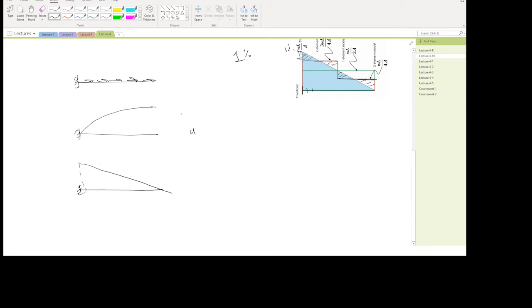So both of them are related. The stress or the strain is the rate of change in the displacement. And if you look into the parabola, you'll see that the derivative of the parabola at this point is 0. So this is why you have 0 value for the stress. And then the derivative of the parabola is maximum at this point, and this is why you have the maximum value for the stress at this point.